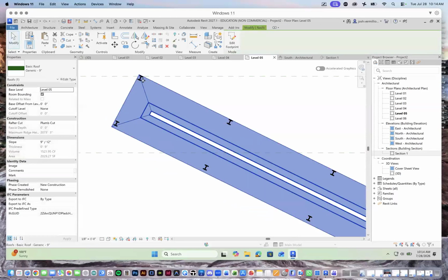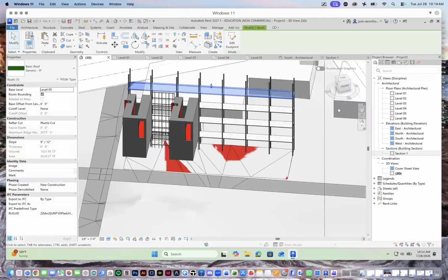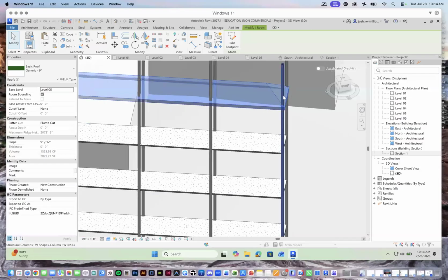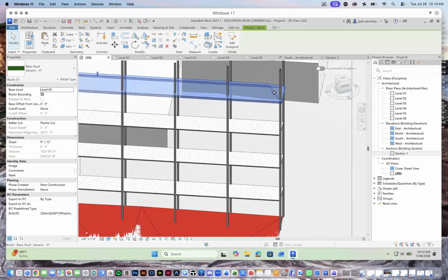Right now, here's the bad thing about this, right? Look at this roof. It's terrible. They wanted to make a hip roof. That's completely inappropriate for what we're doing. That's just silly. It looks like a Hampton Inn in Louisville, Kentucky or something, right? That's not what we're going for at all. And so if I select that roof, you can see that it has a slope of 9 inches every 12 inches. I can say 0 and hit apply, and it becomes just a flat roof.